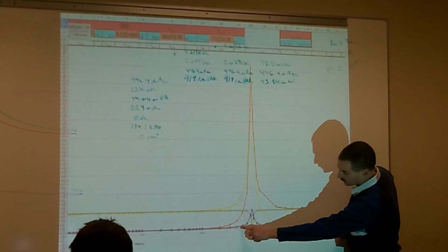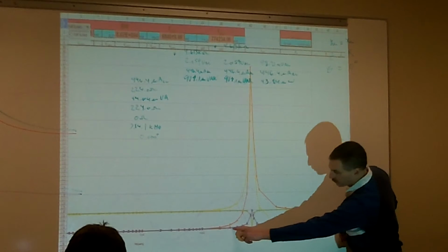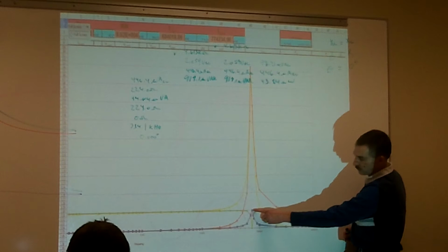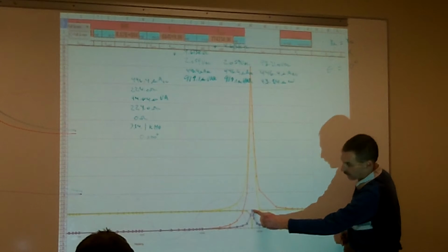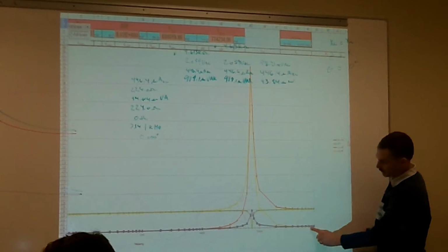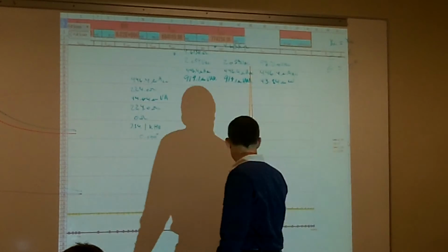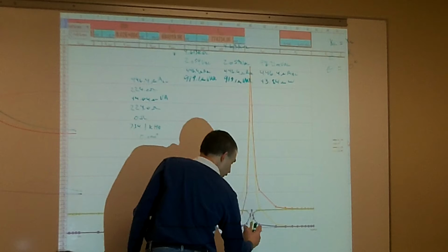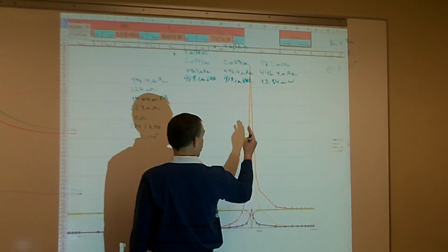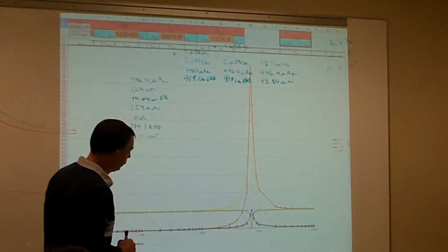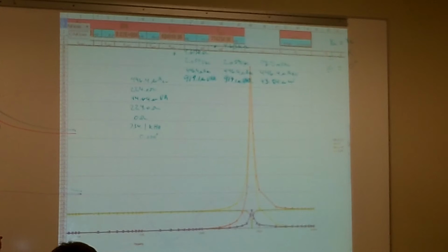And so then you can see that all of a sudden the voltage of the resistor, which is my blue line, spikes up to my source voltage. Then I get past my resonating frequency, and it stabilizes back out and goes back down to 0 volts. So the only time I get any voltage across my resistor is just during this short period when my VC and my VL cancel each other out.